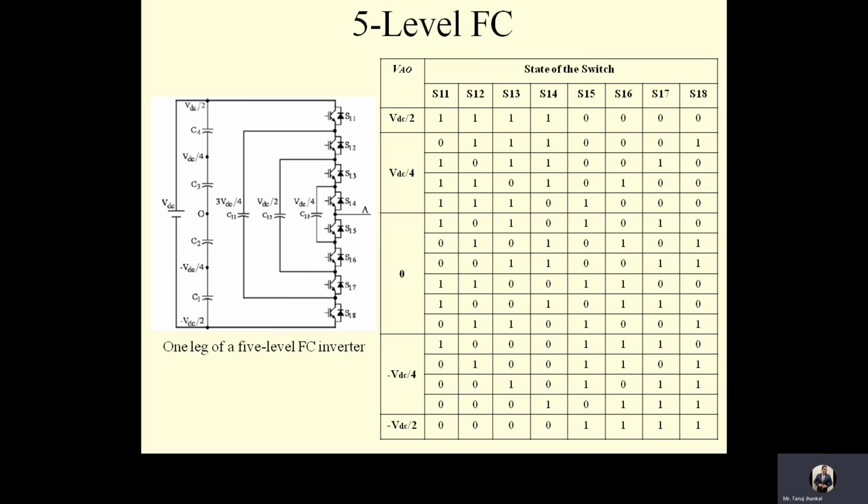The flying capacitor multi-level inverter does not need the clamping diodes but needs a large number of bulky capacitors as floating sources to clamp the voltage. If capacitors with equal voltage rating, which is VDC divided by n minus 1, as the main switch are used, an n-level inverter will need (n minus 1) into (n minus 2) divided by 2 capacitors per pole as floating source, in addition to n minus 1 main DC link or DC bus capacitors.